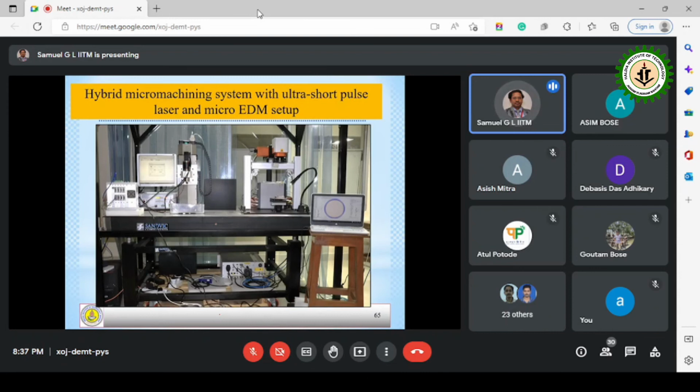So actually there are applications called micro heat exchangers, where heat transfer is the main important phenomenon. There the surface area plays a very important role. As we know, when you make fins, why do we make the fins? To increase the surface area. The more the contact, the more heat will be taken away. Right, sir. So in micro heat exchangers, we use this phenomenon of increasing the surface area by using these textures. You're right.